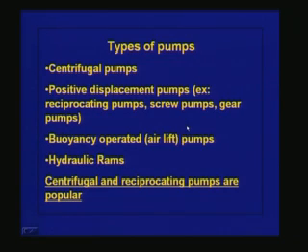Now what are the different types of pumps available, and which of these pumps are more commonly used in water supply schemes and sewerage systems? The types of pumps are centrifugal pumps, then positive displacement pumps, for example reciprocating pumps, screw pumps, gear pumps, all of which are positive displacement pumps. Then buoyancy operated or airlift pumps, and sometimes we also have hydraulic rams. Among all these types of pumps, the centrifugal and reciprocating pumps are the most popular in water supply schemes and sewerage systems.